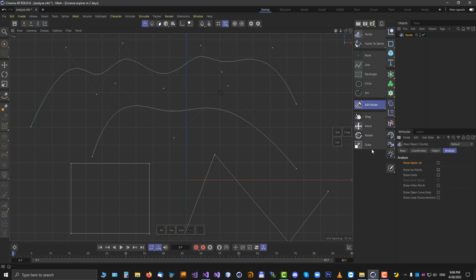The additional 2 options are for displaying knots and knot values. Knots are essential properties of Nurbs. If you don't know what knots are, don't worry about it. Sometimes you need to display them, especially for Nurbs surfacing tools. They are critical. Knot values are about the parameterization of the curve. As you can see, the value of the knot goes up as it goes along the curve.